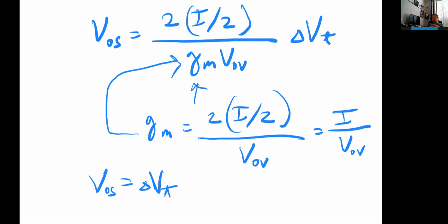So we have seen three effects for the output offset voltage: due to the difference in the RD, due to the difference in the Ks, and due to the difference in VT. So we have expressions for that. And one way to bring all that together, because we looked at it in the spirit of a partial derivative type of analysis, is this.